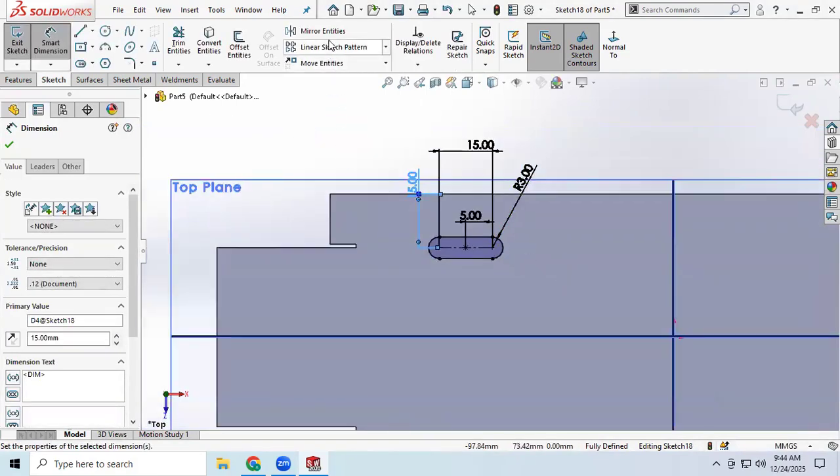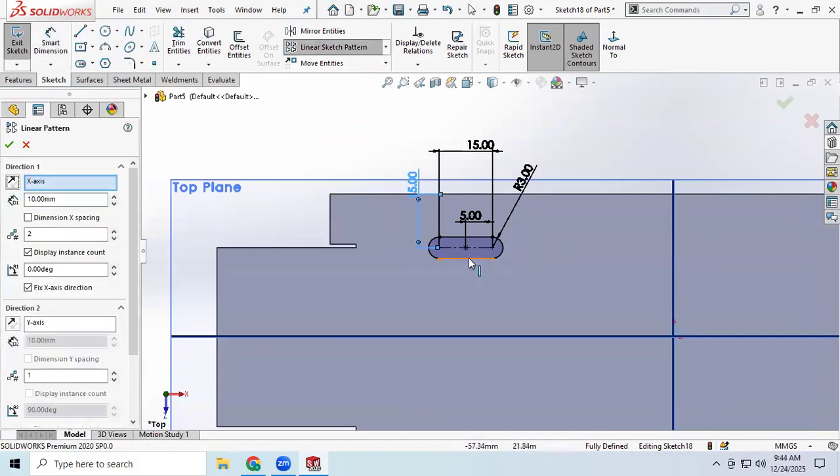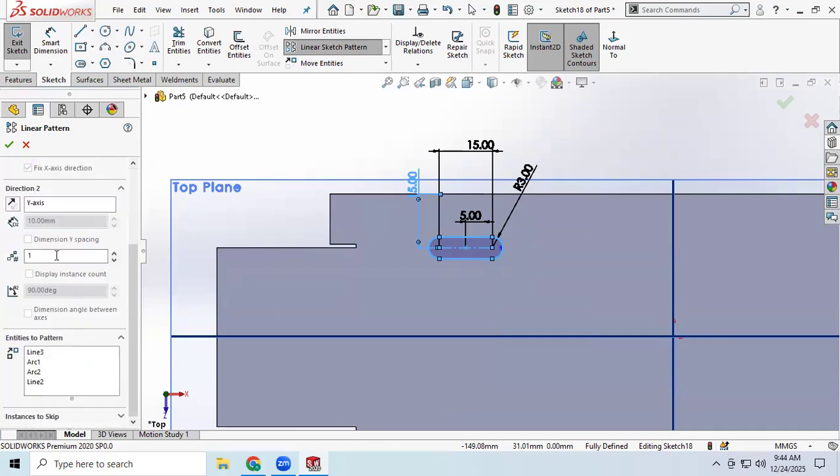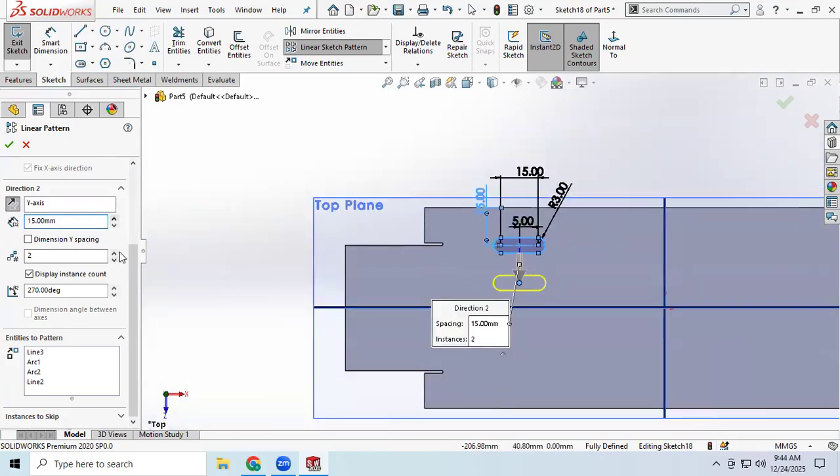After this, I want to do this sketch better. Select this, perfect. And then I don't want to do it as x-axis. I just want to do it in this direction of y-axis, so reverse the direction. Apply the distance as 50. And then increase the depth. I just use 12 mm. I think it's good. This is all good.